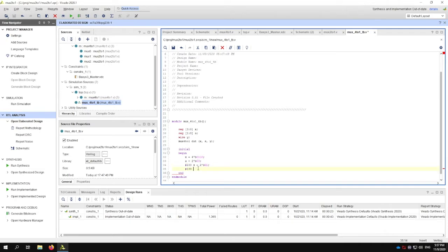So after another 100 nanoseconds, I'm going to assign S another value. I'm going to give it the value 1, 0. So again, what will I expect to see in my output waveform? I'll expect to see Y equal to 1, which is this bit.